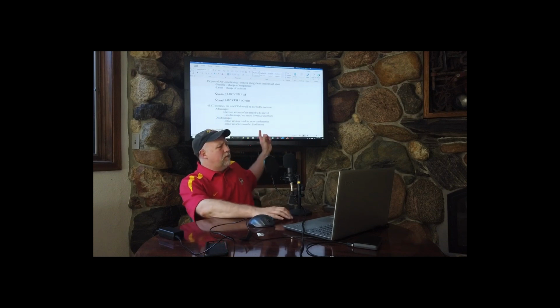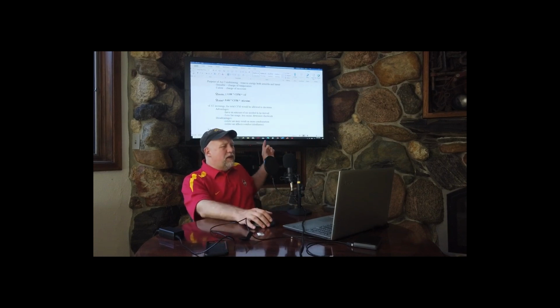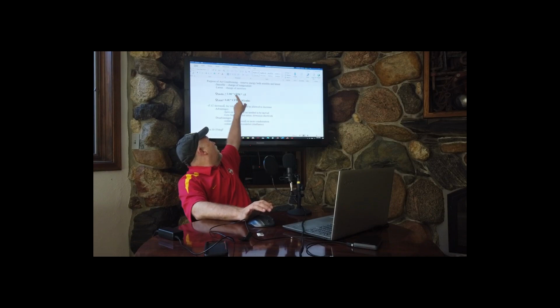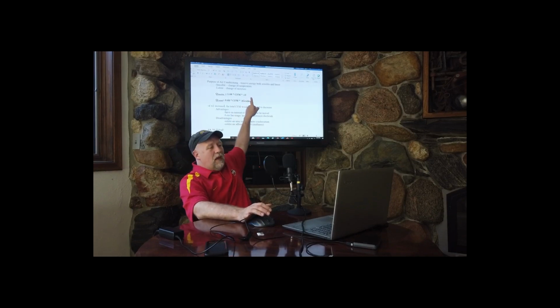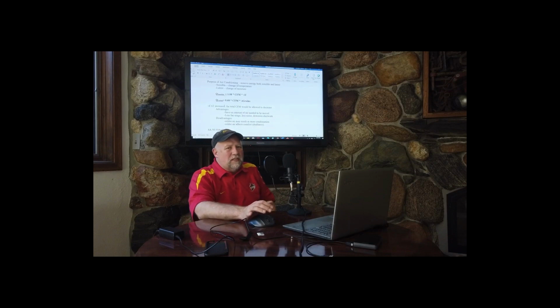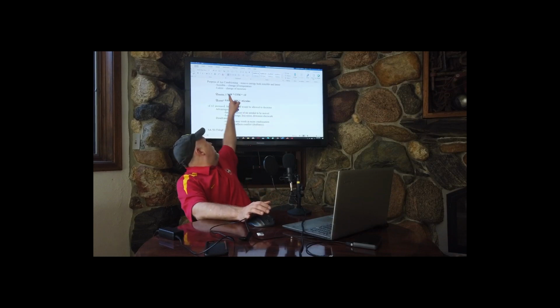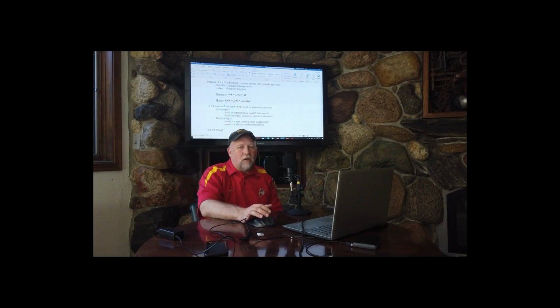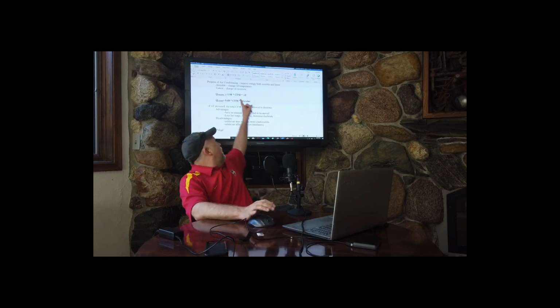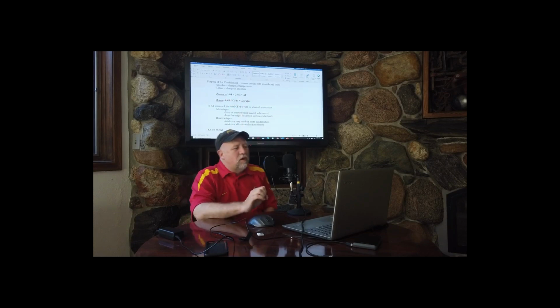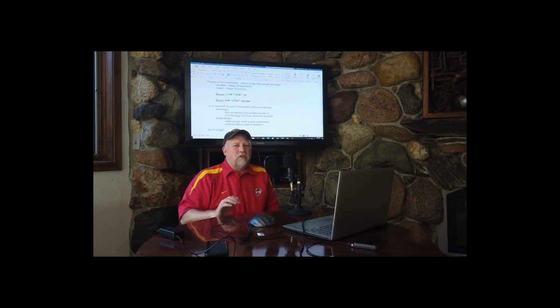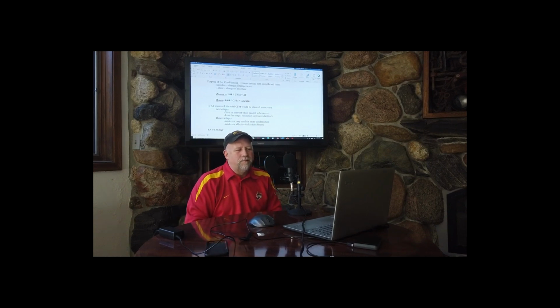So notice this though. If the delta T here, the 1.08 CFM delta T, changes, in other words, if the space is at one temperature and we make the supply air temperature colder, if the heat gain is a constant for a little bit, I can supply fewer cubic feet per minute of air at a cooler temperature to keep the room 72 degrees.